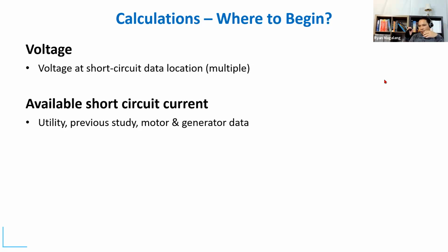And the objective ultimately in that analysis is to know what level of protective equipment they should wear when working in such panels or devices. And in order to do that, one of the things that needs to be done is short circuit analysis in order to conduct an arc flash analysis. So that's another application of short circuit analysis.